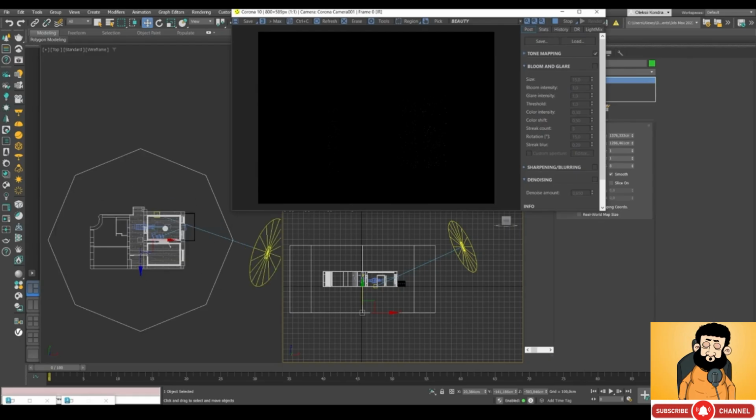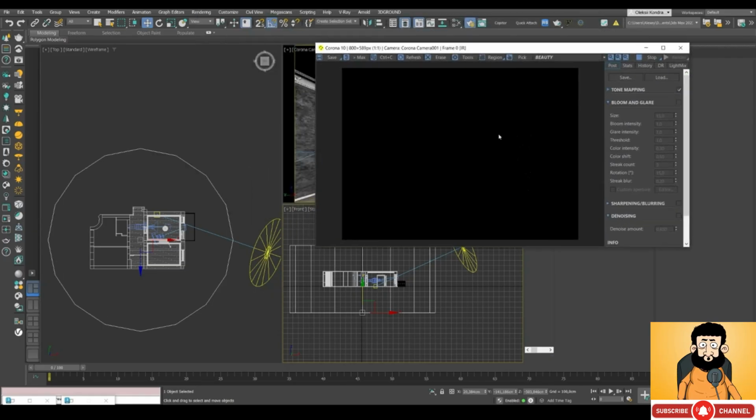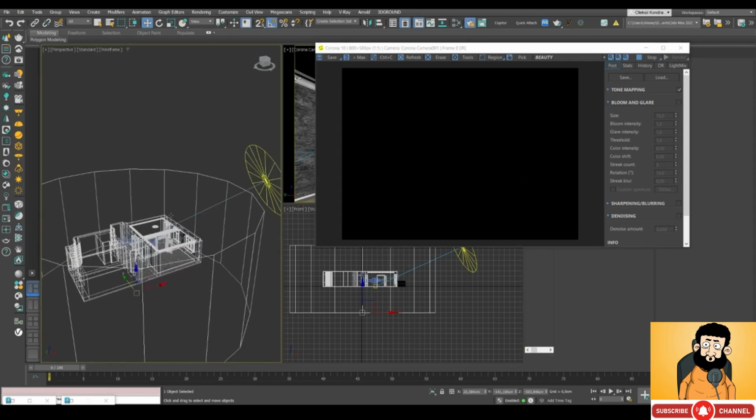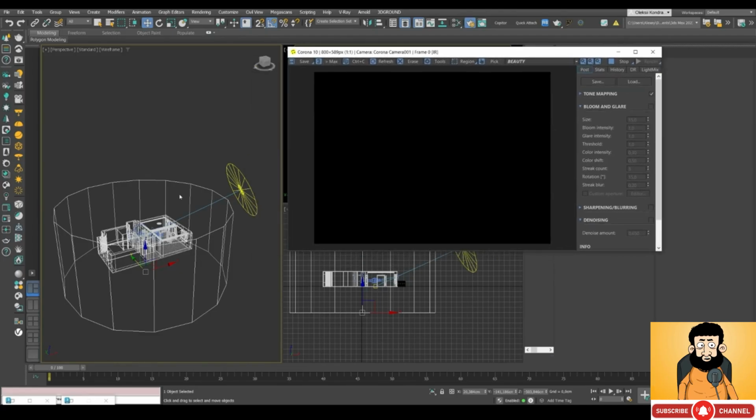So the main thing is that each camera in your scene is perpendicular to the background. The background should never be at an angle to the camera. So we'll increase the number of sides to 16. The render has turned completely black. That's because we're inside the cylinder, and we need to edit it.